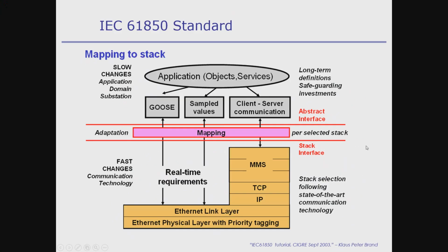these are the communication services I'm talking about. There are 3 types. You can have 3 types of communication within the substation with this standard. Okay. Client server communication, okay, which is slower. Let's say you want to transfer fault records from an IED to a substation computer. Okay. So it's connected to the substation station bus and so on. So it's not time critical, and also it's a lot of data. Your fault record is going to the station computer, right?